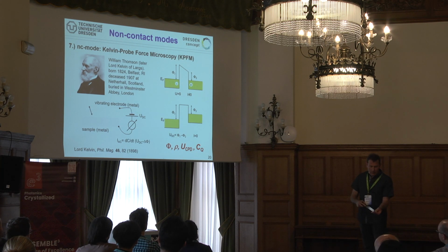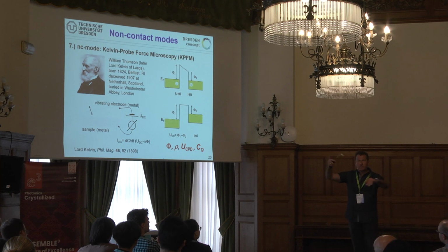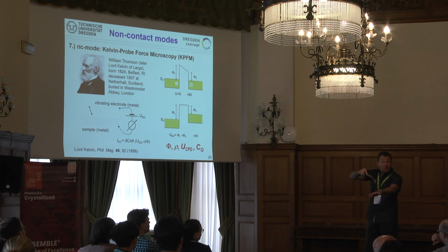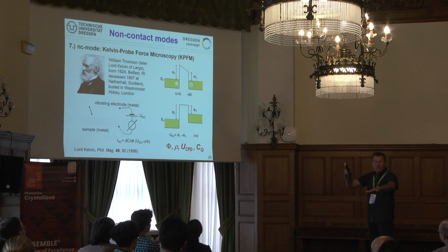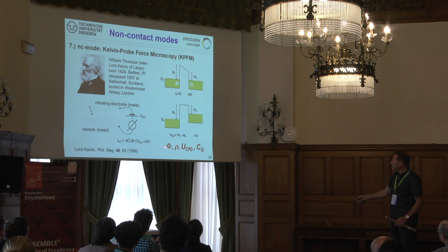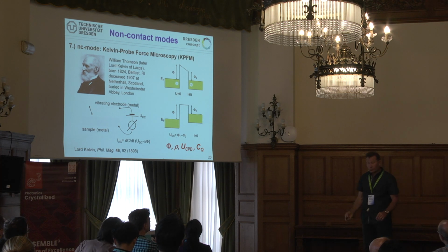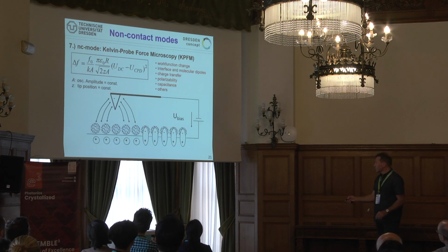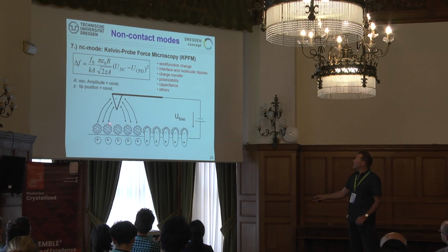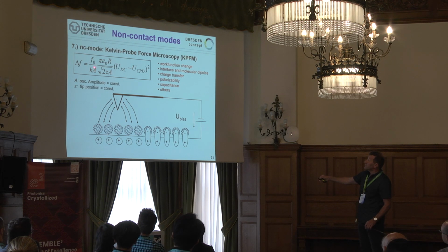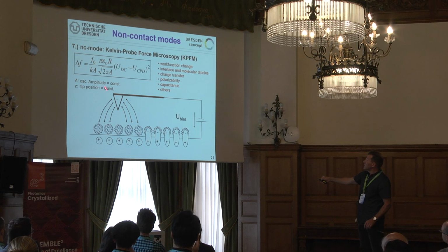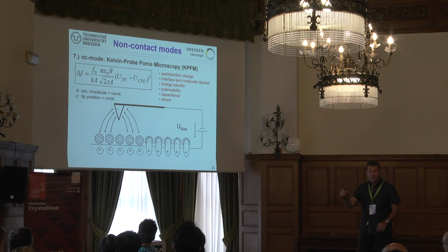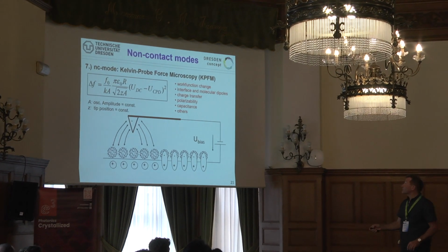So if you want to work now with this, we put the tip on it, and we want to measure that. We want to have it quantitative. Let's see whether we can do that, and we're not going too close. And in fact, I want to convince you, yes, you can really measure this work function. You can measure the charges that are relevant for that. You can measure the contact potential difference and even more, capacitance. So this is basically what we have. We have the cantilever. We are vibrating this cantilever at a certain frequency f0. That's my oscillation frequency. And for the moment, it's not the atomic force that is relevant, but really this electrostatic force.